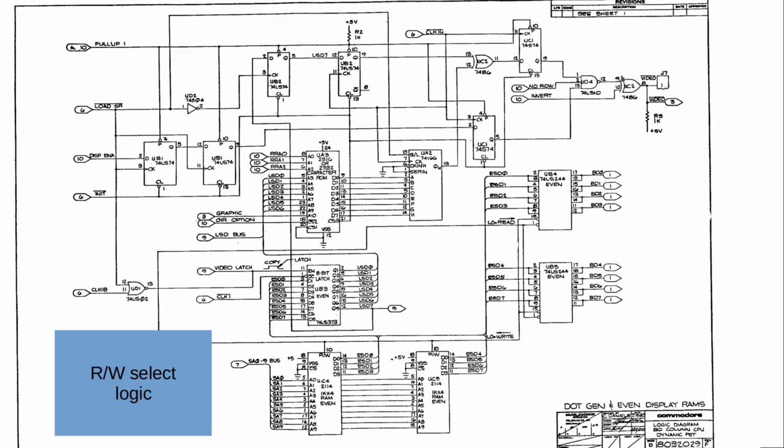Some more output stuff, more output control, and then it is actually output. This here is actually to sync the display enable again after it has been delayed here. This is synced to the 16 MHz clock, so it's basically the same clock domain as the pixel output, so we don't have any artifacts at the beginning of a character of the raster line or not.